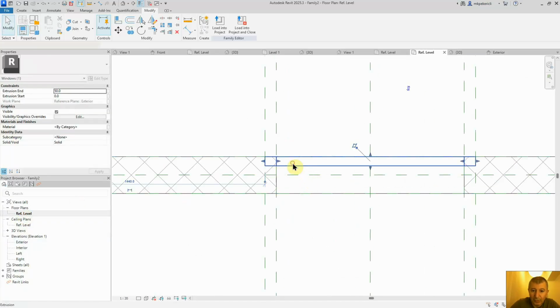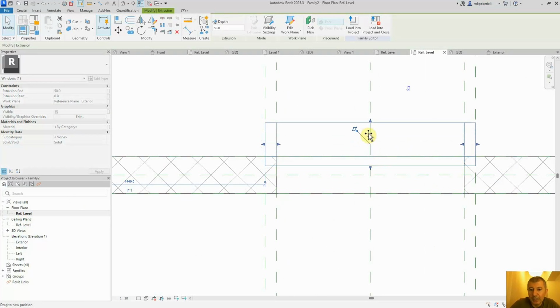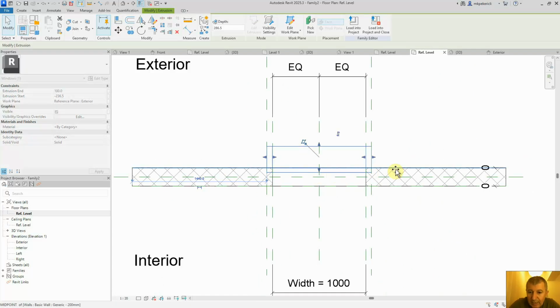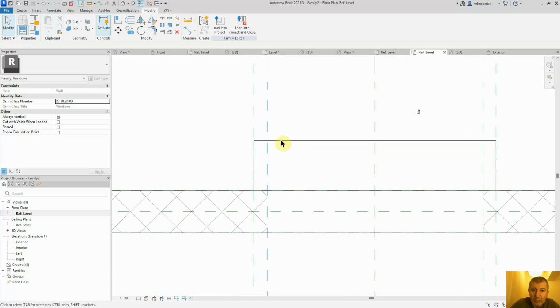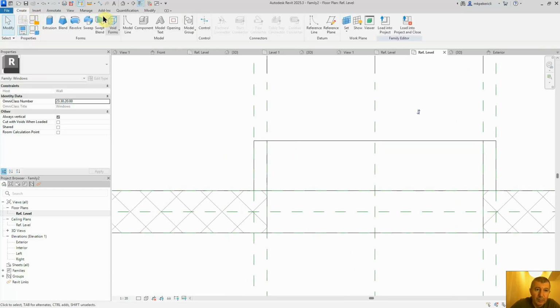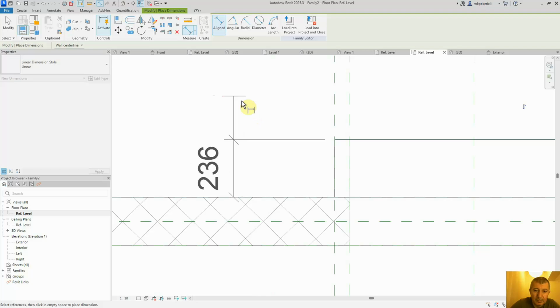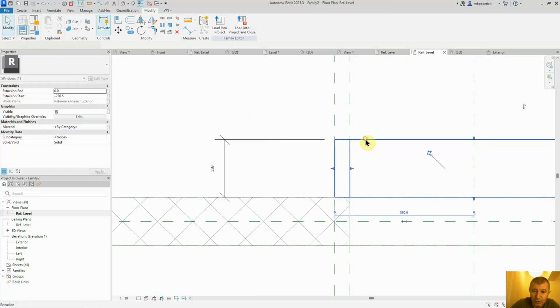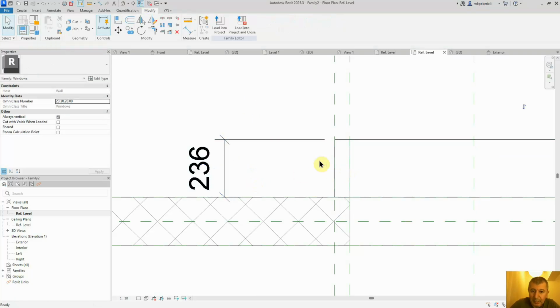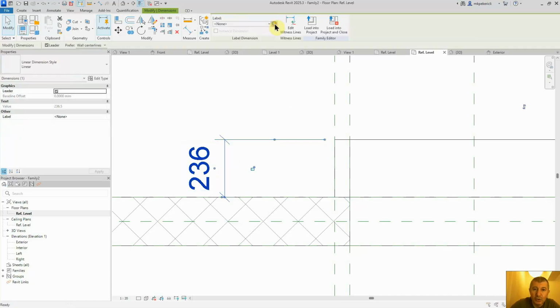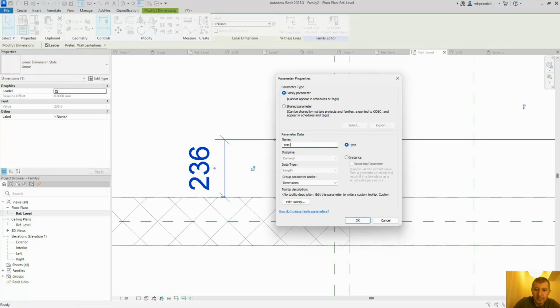Yes, this is the thing that we created, but we want it to be on the outside. We move it out like that first, and second, we move this edge and place it at the edge of the wall like that. Perfect. Now we need to define the depth for this trim, and for this I create a new parameter, trim depth.